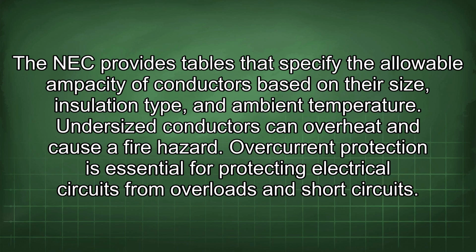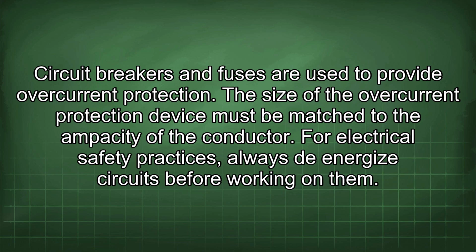Overcurrent protection is essential for protecting electrical circuits from overloads and short circuits. Circuit breakers and fuses are used to provide overcurrent protection. The size of the overcurrent protection device must be matched to the ampacity of the conductor.